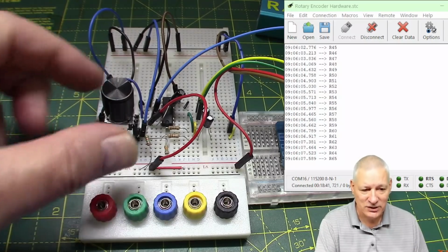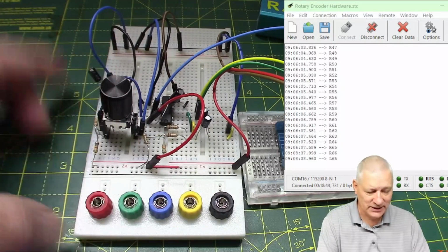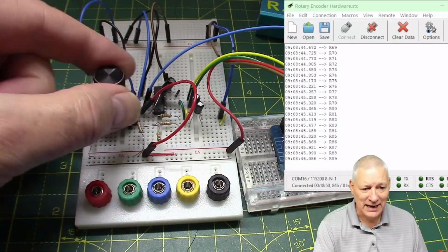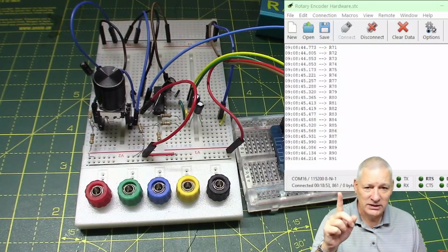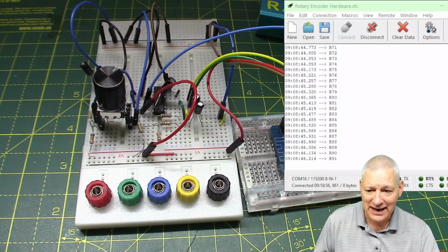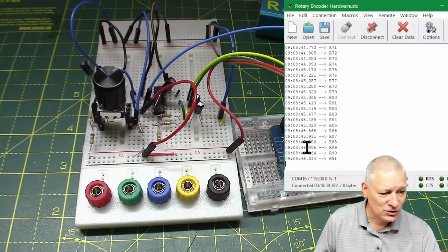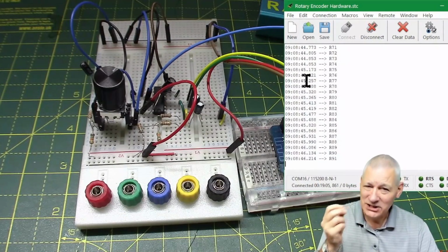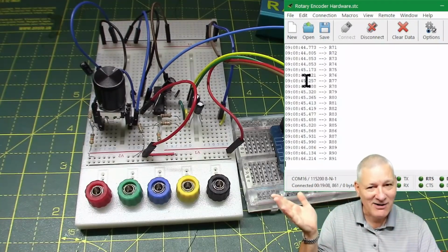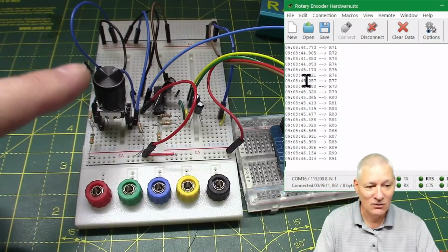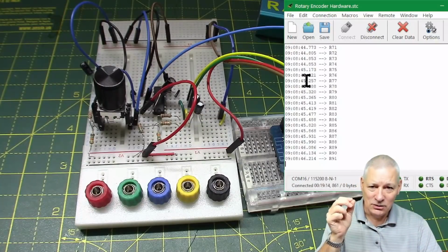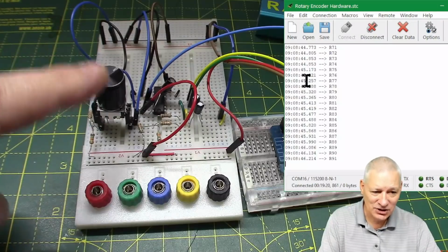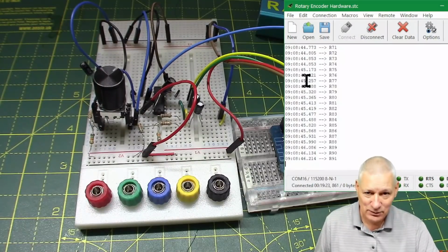Now, 60 RPM is one revolution from where it is now. You can see it's at the 12 o'clock position, yeah? So that means from there all the way round back has got to be done in a maximum of 1 second. And I've been looking at the output on this screen here to make sure I don't turn it in more than 1 second, and it's very easy to do. 1 RPM is in fact quite slow, pretty much about what my car accepts. So who knows, in my car there might well be one of these. So not only are we looking at switch bounce elimination, we're also saying you just cannot turn these that fast and expect to get a sensible output.